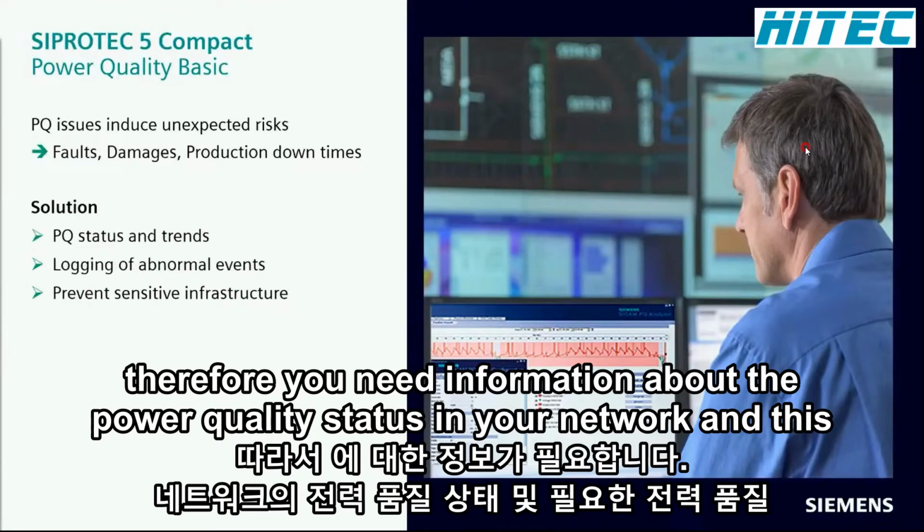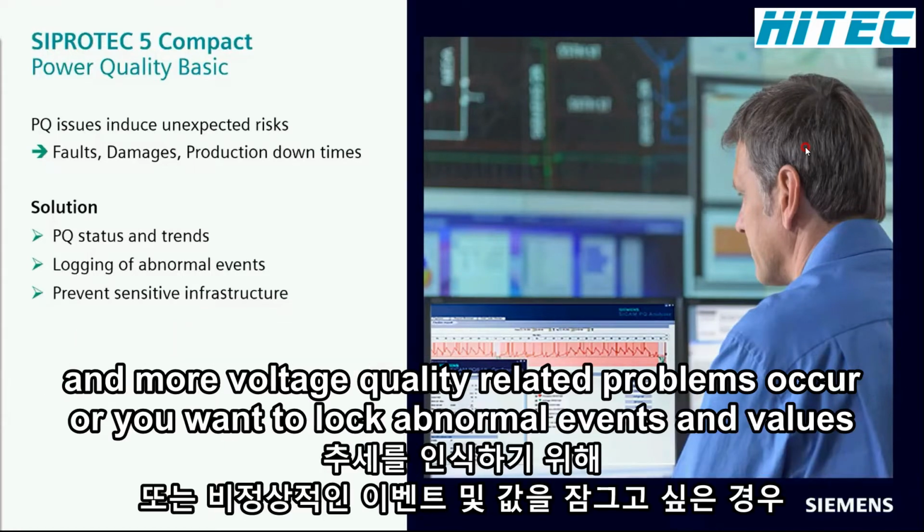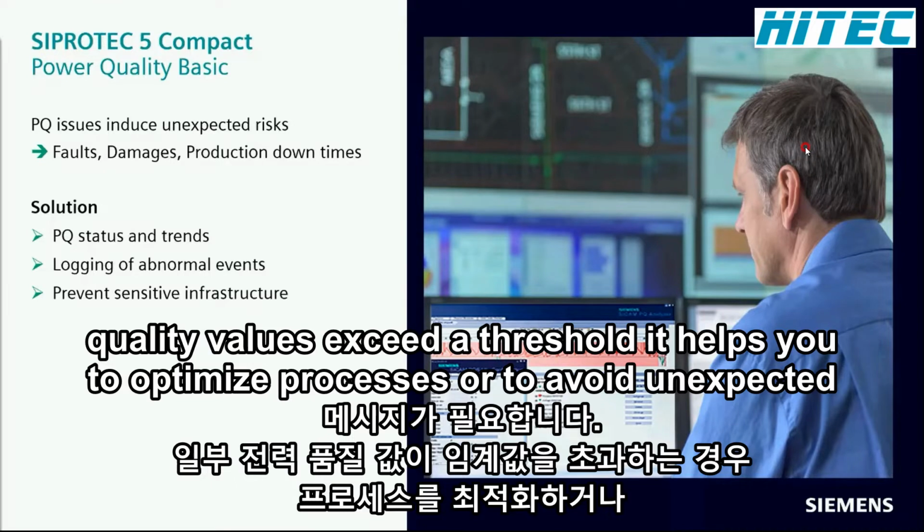Therefore, you need information about the power quality status in your network, and this by using power quality basic functions. They are needed for recognizing trends, because as mentioned, more and more voltage quality related problems occur. Or you want to log abnormal events and values. Or you need early warning messages at sensitive areas or critical infrastructures if some power quality values exceed a threshold.